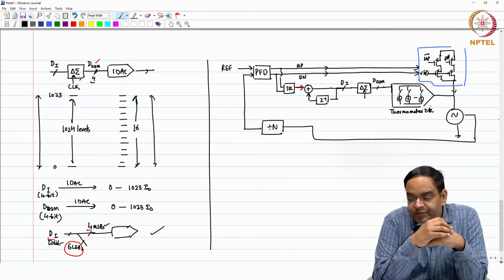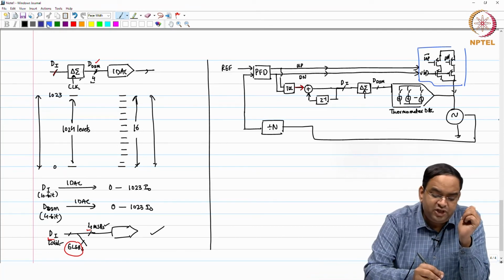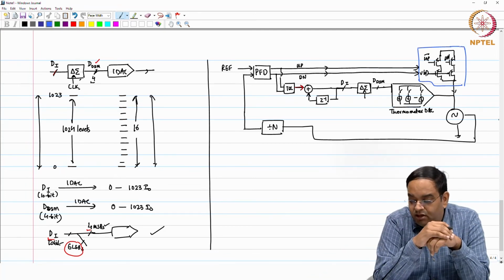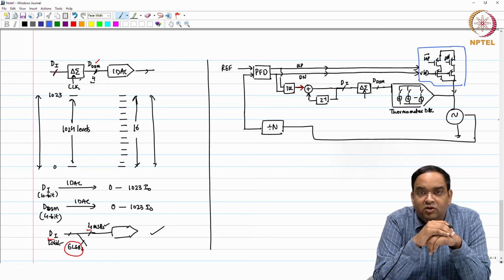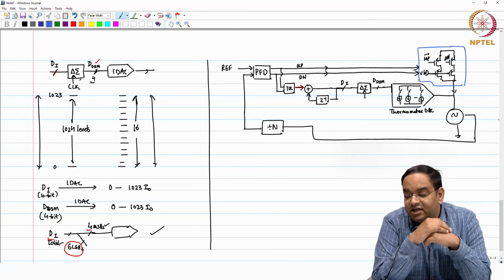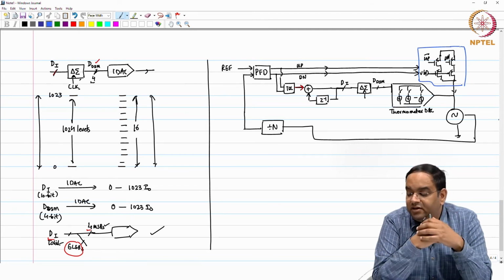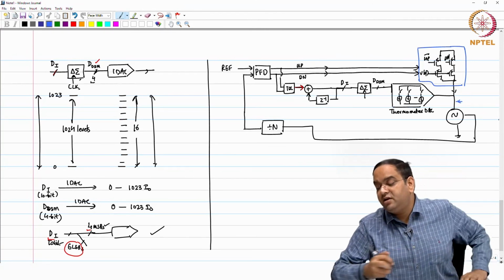Now, as you go on implementing and realizing a certain resolution, you will not feel that much of an issue with the proportional DAC, but with IDAC implementation, the range versus resolution trade-off will always be there. So, you come up with some other ways, you can give extra current as required, that will be for you to read about, and then you can have an extra DAC which feeds into this oscillator. That is perfectly fine.